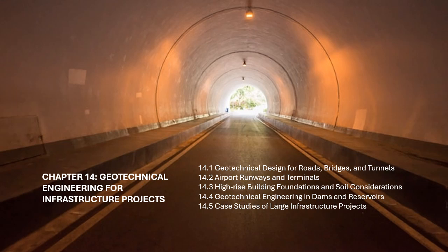Concrete gravity dams. These dams rely on the mass of concrete to resist the water pressure and are typically constructed in narrow valleys. The foundation must be strong enough to support the immense weight of the concrete structure.